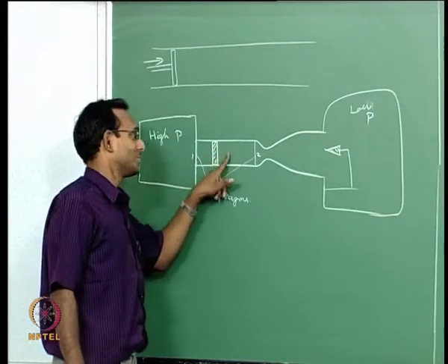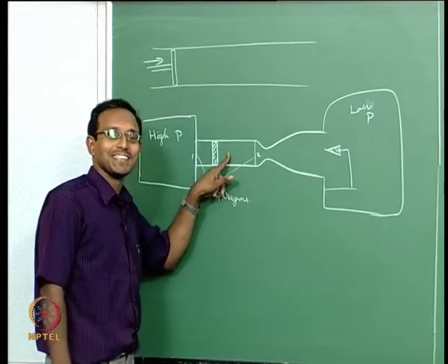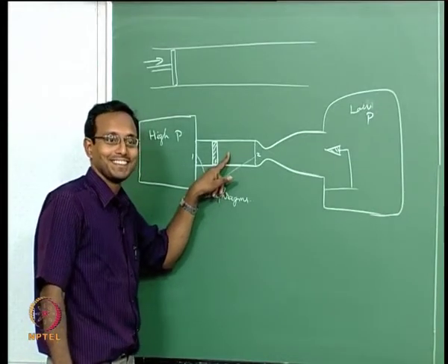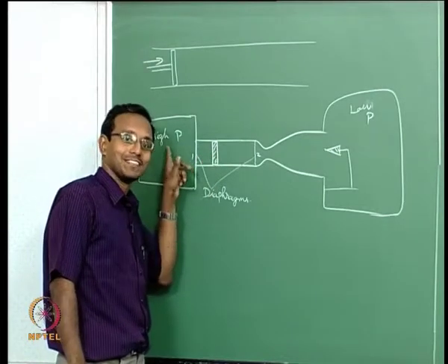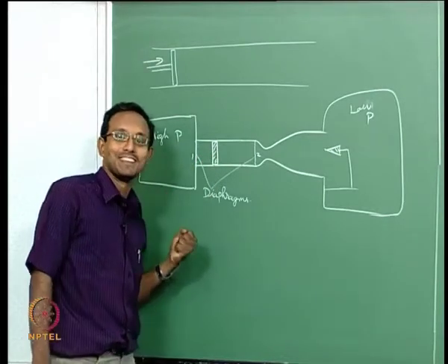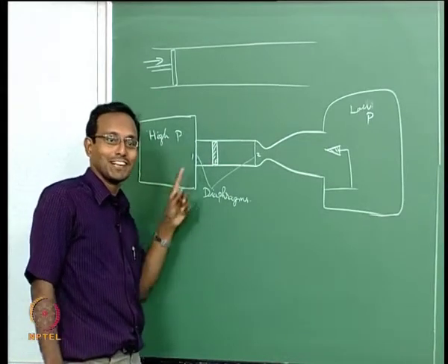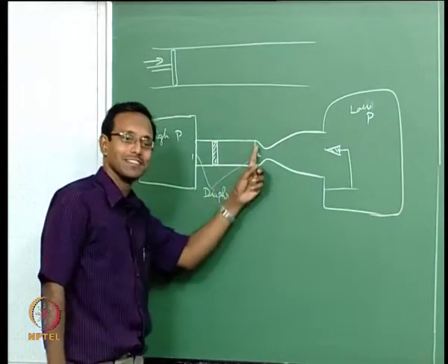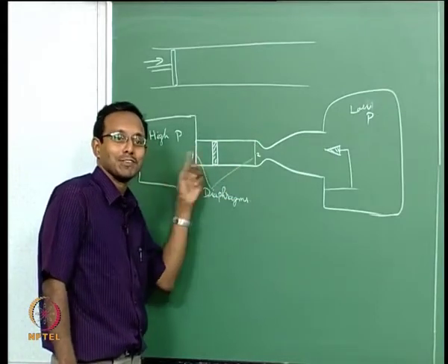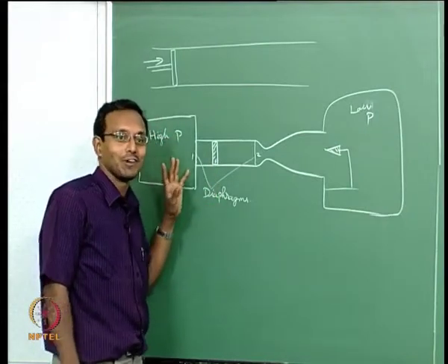What gives the energy to the second one? This piston movement. What gives energy to the piston movement? The first one. Which one will have more energy? The first one. In theory, it will be the first shock that will create more. Then why do we use this? I just remove this and that shock can go and hit this. Then that becomes your reflected shock tunnel that you already know. That is one design we already have talked about.